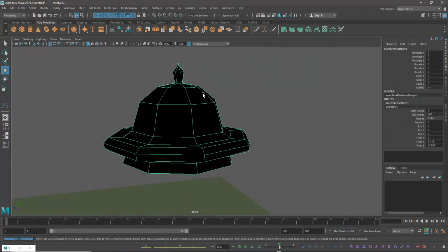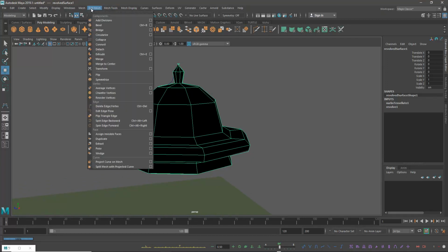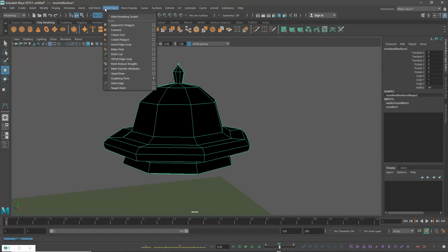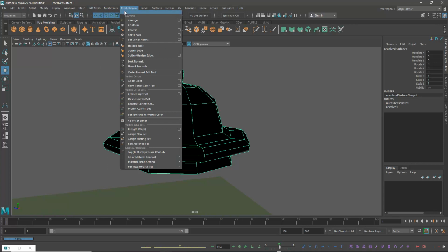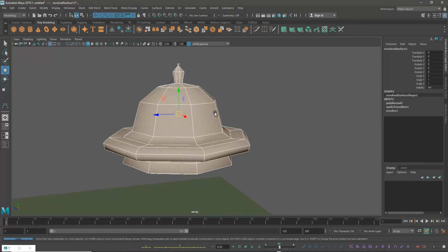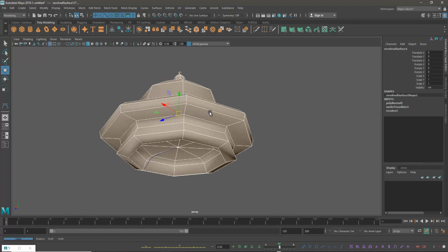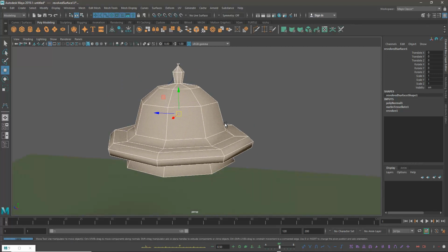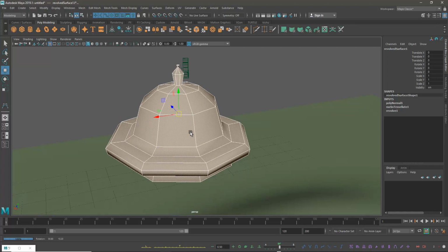Simply you can select that mesh and go to mesh display, reverse, then automatically you can see the normals. I hope we discussed normals in the last class. We'll also discuss in the next classes what normals are. Normals are nothing but face directions, whether the face is directing towards outside or inside. That is what we will see again. So I made this one.